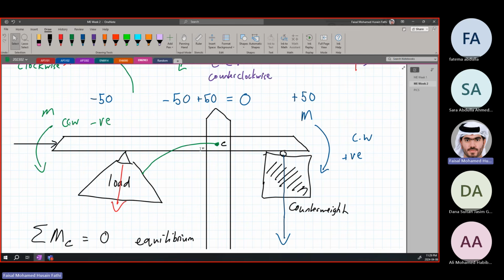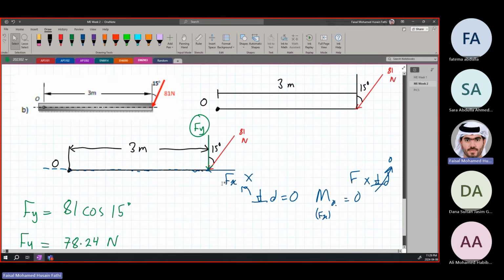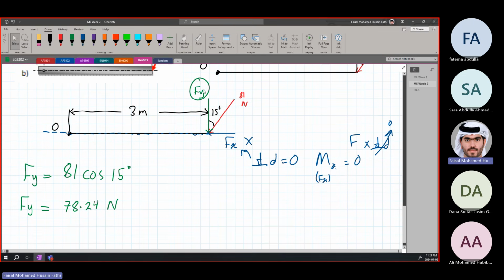Right? You're not going to push it from the end of the pen, or from the beginning of the pen, the point where you're writing with, because that will never bend it, not even in 100 years. You have to apply a force perpendicular to it, in a perpendicular direction, not parallel or along the same direction. This is the exact same idea why this force Fx does not affect any of the moment around O, but for Fy there is a moment caused due to it because there is a perpendicular distance.